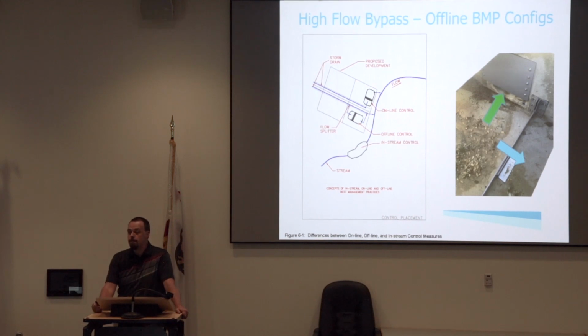Why would you want to adjust that after you design it? Well, one thing is we designed the 6-inch weir wall for the water quality volume that we were wanting to do for our project. And if we start getting really good numbers, we want to be able to divert some more water. The idea there too is we didn't want to inundate the facility with the 12-inch weir initially while we're doing plant establishment. We didn't want them to drown if there was some ponding. So we went with a 6-inch with the possibility of adjusting it.